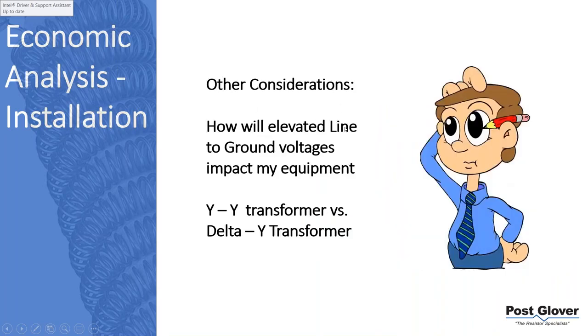I did mention before, how do you deal with line to ground voltages elevated? Now, on low voltage systems, once again, I'll repeat myself a little bit. It just depends. If you have a lot of UPS, or a lot of drives, et cetera, that are not made to handle elevated voltages, there could be a cost impact. There's just so many variables that it's hard to quantify. I will tell you this though, on low voltage, it's much less likely than at medium voltage. You have a large impact at medium voltage. So this conversation is geared towards low voltage.